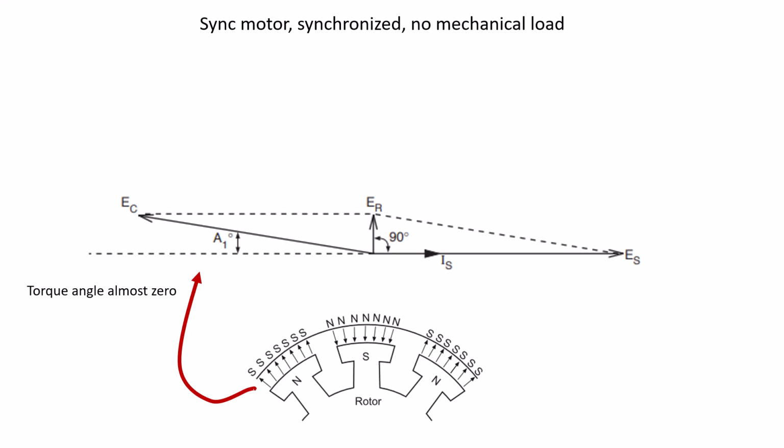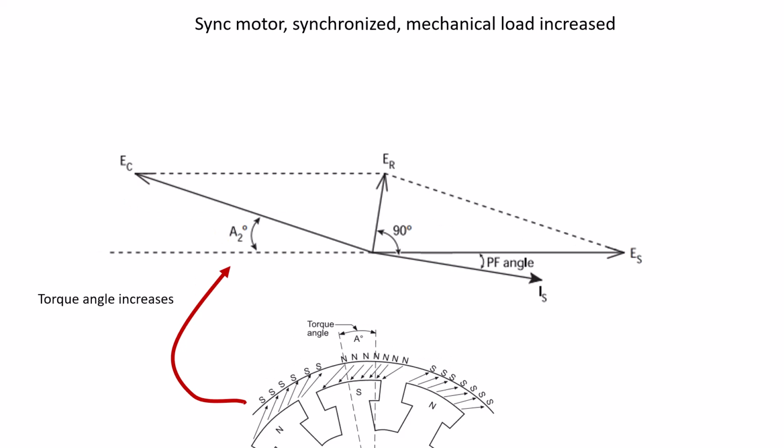Remember, we said that the resultant voltage is a product of a vectoral addition of E of the coil and E of the stator. This means that if there is pretty substantial or equivalent magnitude to each of these, we should see a resultant that's quite low. A low resultant voltage divided by the Z should then result in a low stator current.